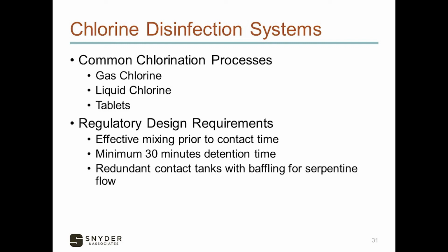Now, here's the other piece of this. We've got to have contact time. We've got to have a minimum period of 30 minutes of detention at high flows. In the case of Iowa, that's average wet weather and peak hourly wet weather. And every state has a standard like this. In a nutshell, it means a long disinfection period. The contact tank of these things can be large. Most systems are required by their state regulators to use something on the order of a baffled 40-to-1 length to width ratio tank. That's a sizable tank.